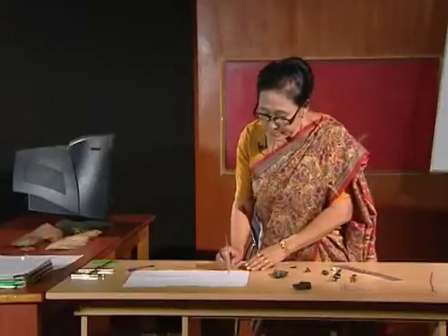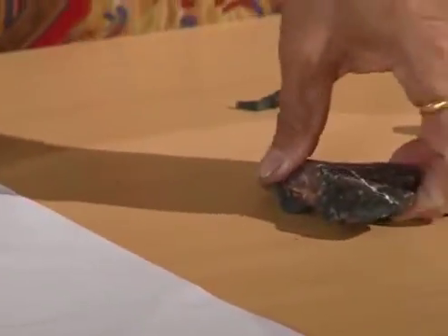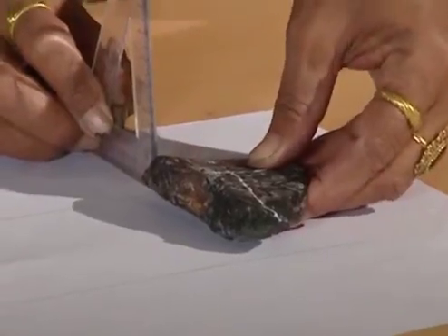The 7th point is, after getting the proper position, the specimen is then transferred to the drawing sheet. While transferring, one hand of the student should hold the artifact with the plastic sheet, and the other hand should hold one set square already placed, affixed to the lower horizontal line already drawn as the lower margin of the specimen.